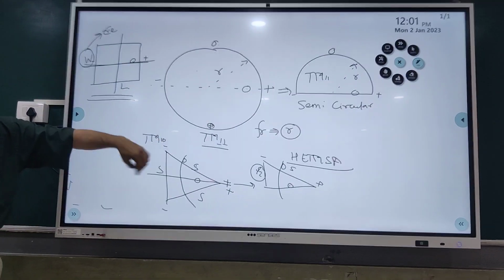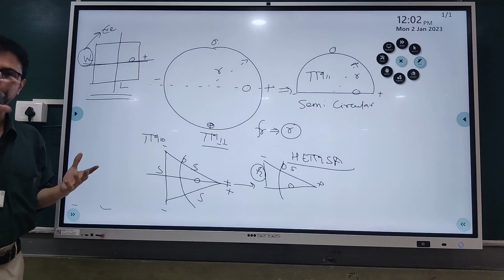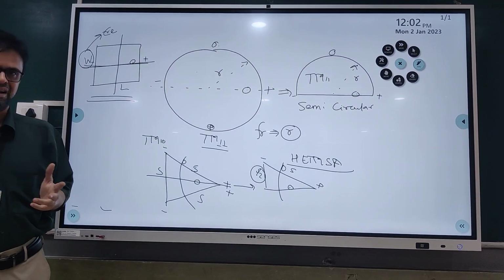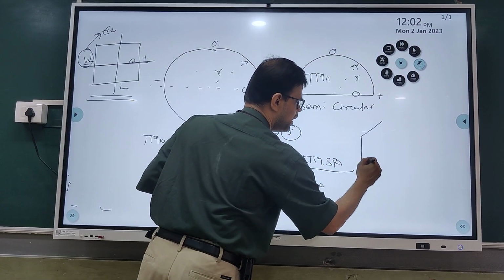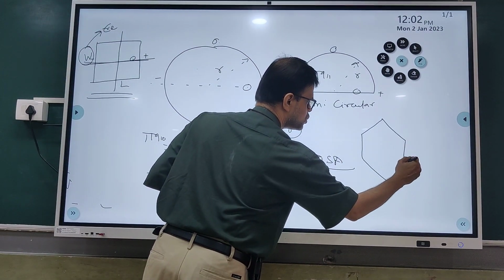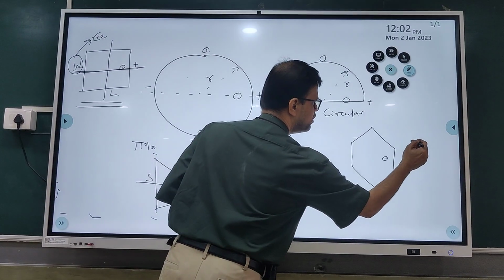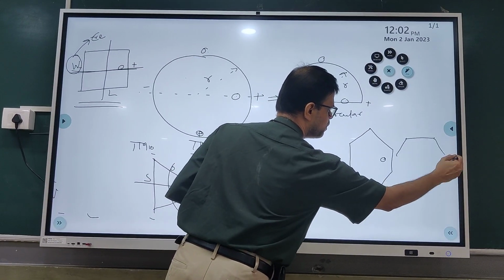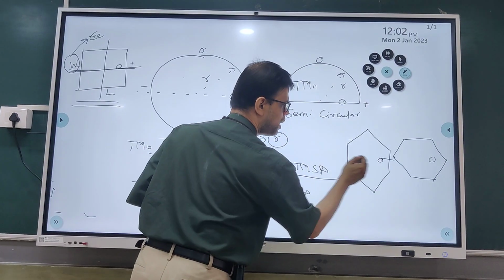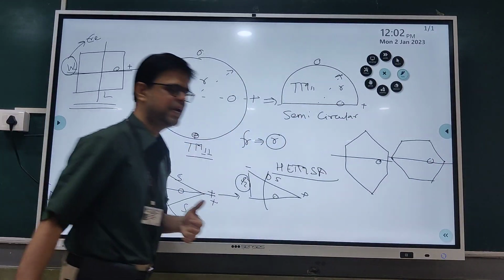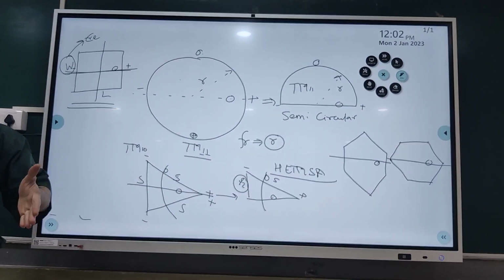Remember this concept: depending upon the shape of the geometry, I can decide and apply the concept to other geometries as well. For example, the same concept I can apply to the hexagonal microstrip antenna, if it is fed over here or if it is fed over here, because two variations are possible. So I can apply this concept to the hexagonal microstrip antenna and realize a compact configuration.